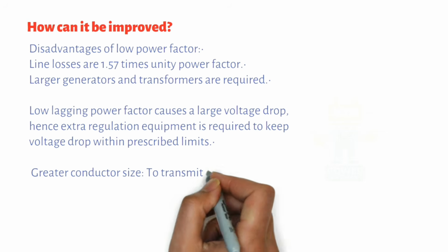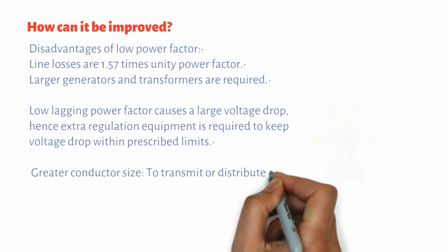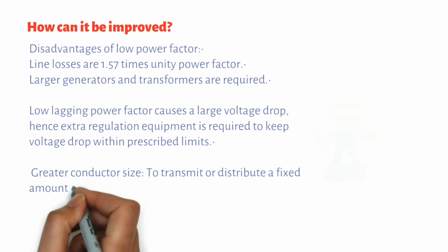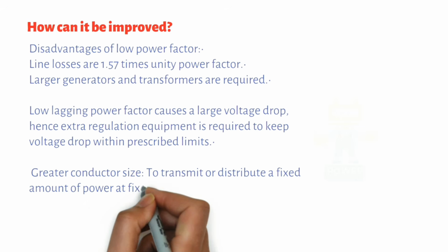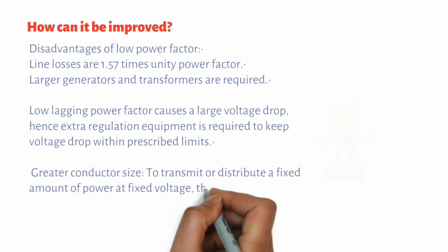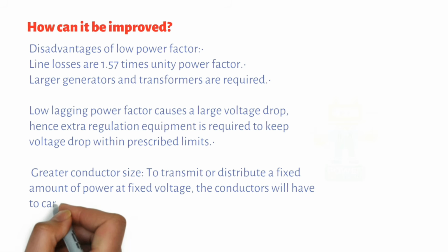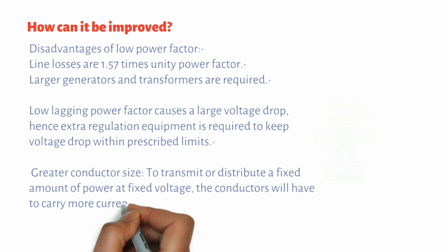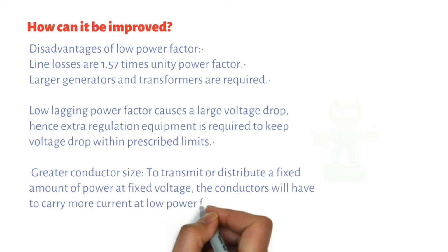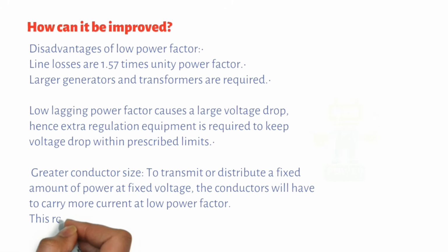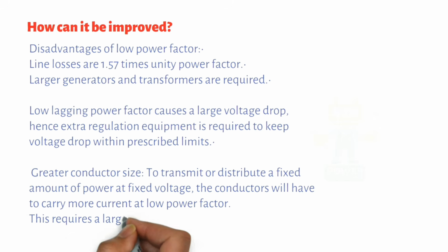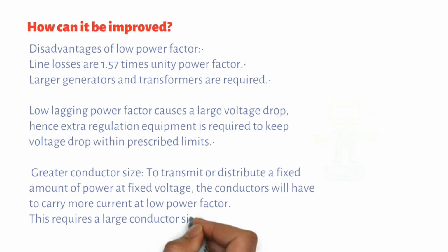Greater conductor size is needed to transmit or distribute a fixed amount of power at fixed voltage. The conductor will have to carry more current at low power factor. This requires a large conductor.